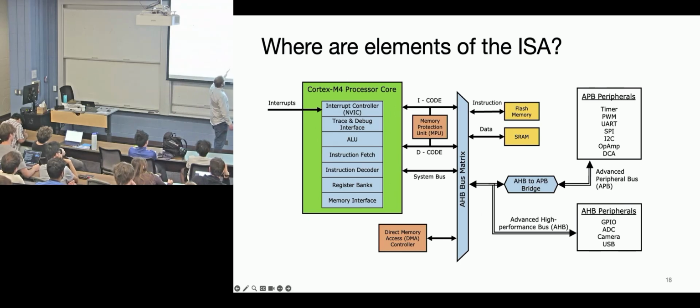There is a high performance bus in between. In this class, we don't talk about that so much because it adds so much complexity that you'd lose the value of understanding how the bridge works. So just assume for most of this class that the core talks directly to the bridge and the bridge talks to these devices. When you do loads and stores, you're literally manipulating these lines to transport data to one of many different destinations, and the address defines that destination.